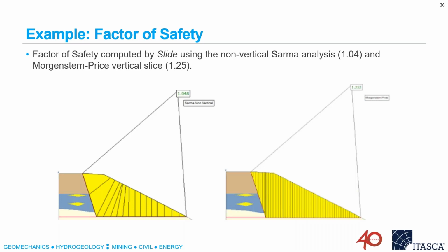It does depend on how the rock mass is breaking up. But in general, the flow rule doesn't have a huge effect. The dilation doesn't have a huge effect, but it doesn't cost you anything extra to put in, say, 5 or 10 degrees and see what happens and see if there's any difference.